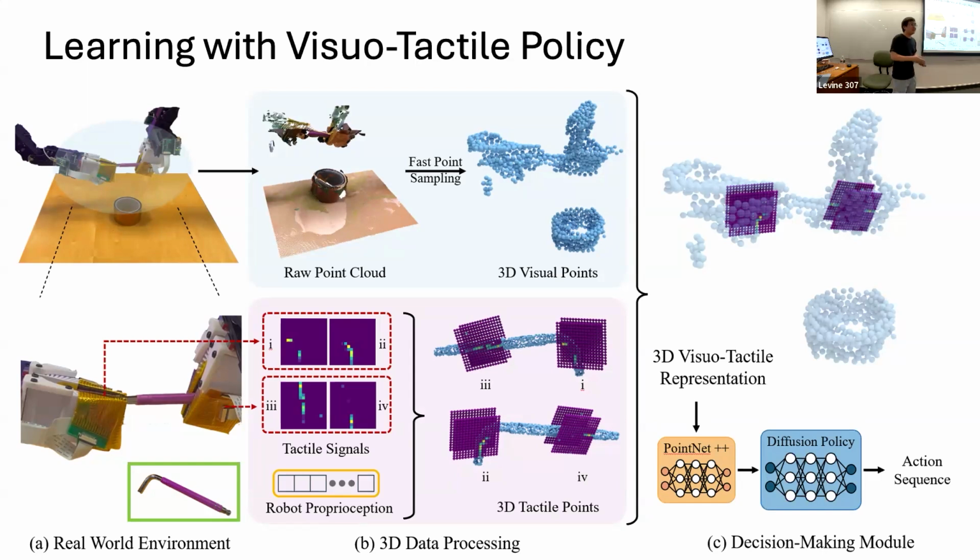We also find similar results: if you train with point clouds, it will train faster. You mean that you need fewer demonstrations? Fewer demonstrations and faster training. Also, here we just want a simple solution that fuses vision and tactile together. We find the point cloud representation is good for fusing vision and tactile and helps build the spatial relationship.